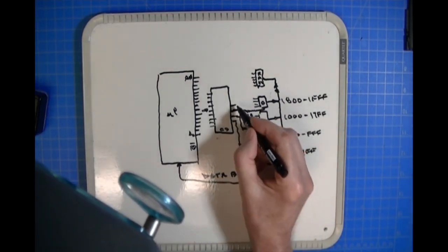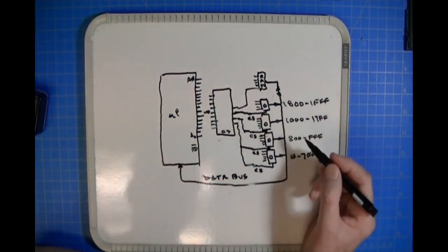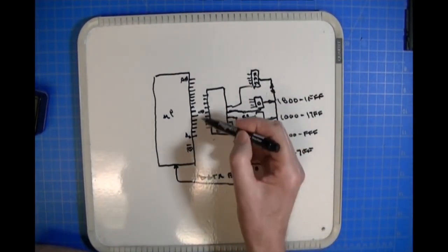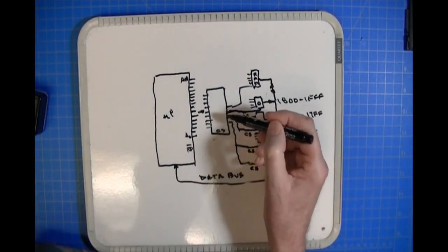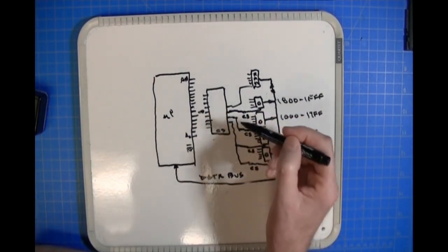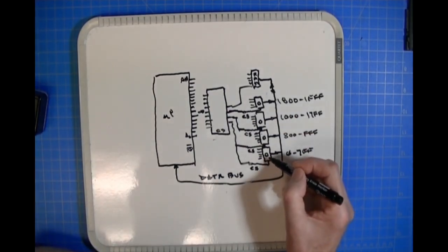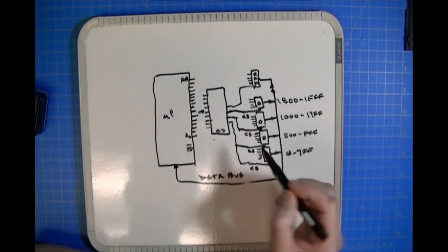Well, I'll just use this one for my RAM. Let's say this goes up to the RAM part. Anyway, when the bits that correspond to the correct address go into the bipolar PROM, you want the outputs of the bipolar PROM to choose the proper EPROM. All right, you can do it with one part.